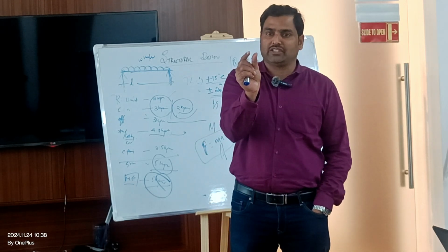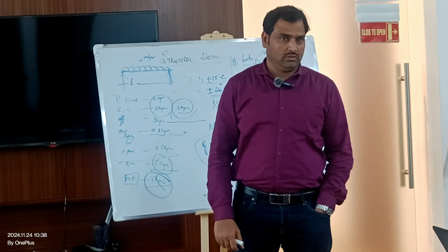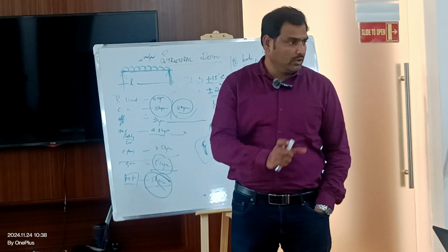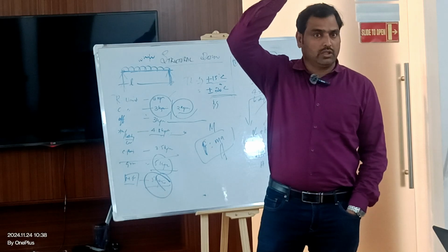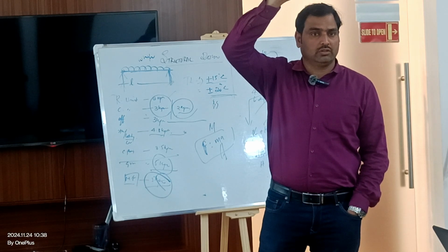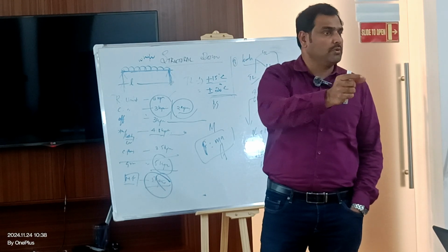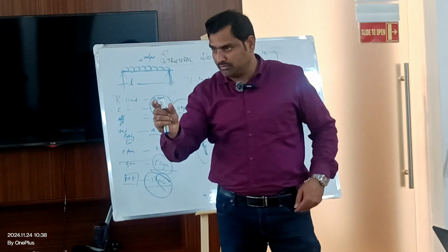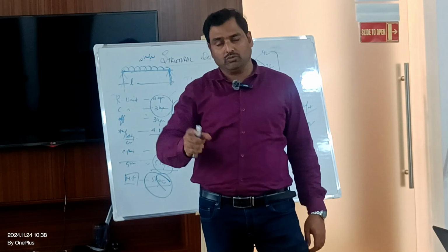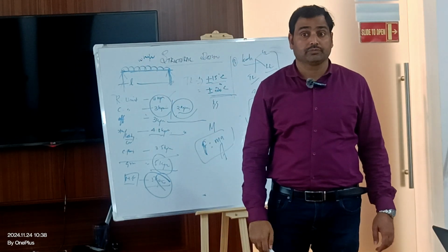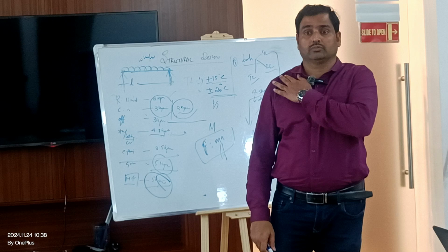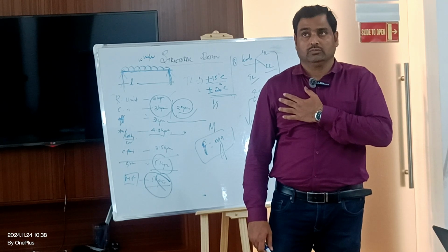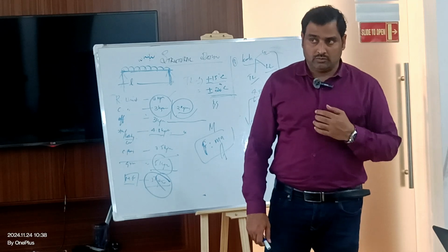How are you going to calculate the expansion joint width? Say 35, 50, 60. So there could be a calculation, right? If you are following maybe a 150 story tower, then the expansion joint may not be the same as 25 millimeter, and it may not be the same as 50 millimeter as well, right? It requires some calculation, isn't it? Yes, this one we had for a cycle track also. We had some concrete cycle track. Initially, they were proposing like 20 or something, but it started cracking everywhere. Then they reduced it, and they asked to come up with a calculation.